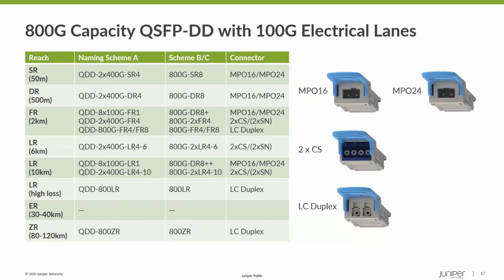The optical connector options are summarized here. One of the things interesting is all this interest in using 4 SN connectors for independent connections for a quad port breakout module can no longer be supported, because we need 8 ports and we can't get 8 SN connectors in this module. So we have to go back to using MPO connector for breakout of the 8 ports of either DR or R1 100 gig optics.